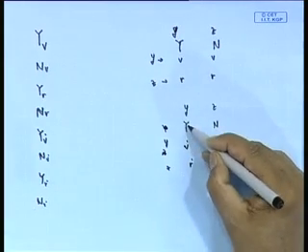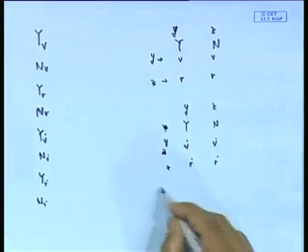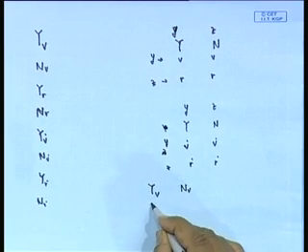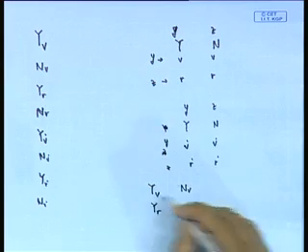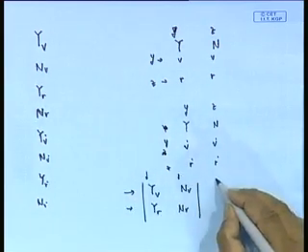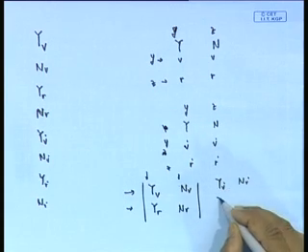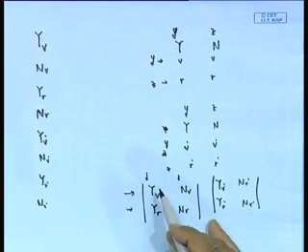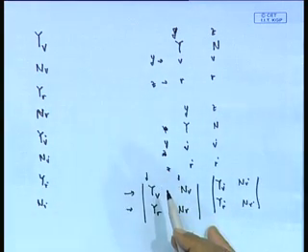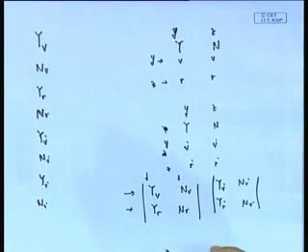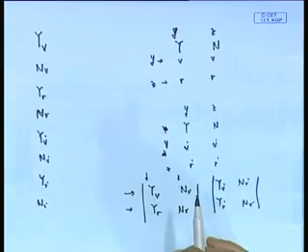You see Y v dot, and therefore, what I mean is that the term becomes like that, Y v, N v, Y r, N r. It is like a diagonal term here, because this is actually the Y axis, and here Y v dot, N v dot, Y r dot, N r dot. I will tell you what I meant by that. See, Y force is the force in direction Y in which the velocity is v. So, Y v is the so called diagonal term, meaning you are trying to find out force in the same direction in which velocity is taken.